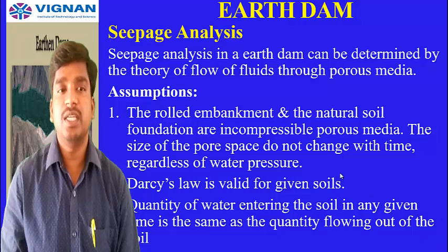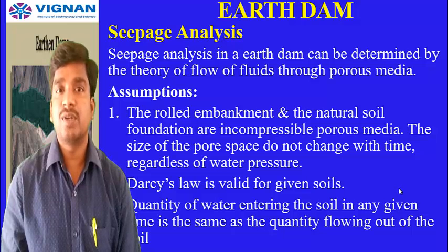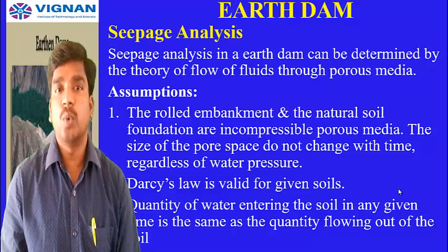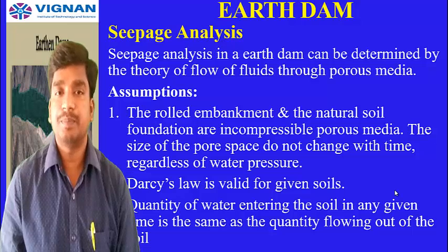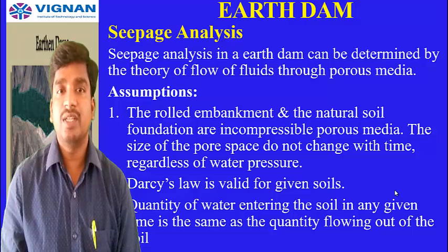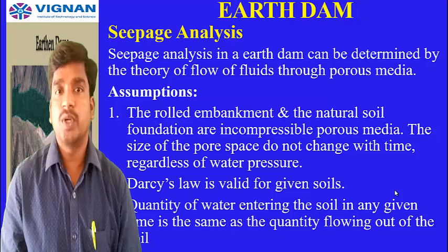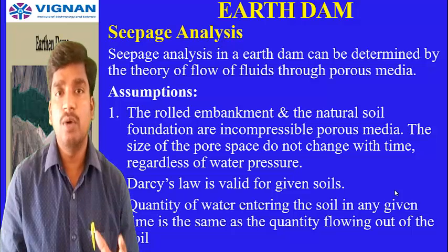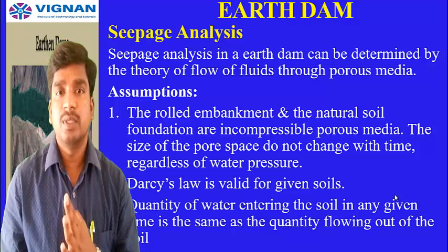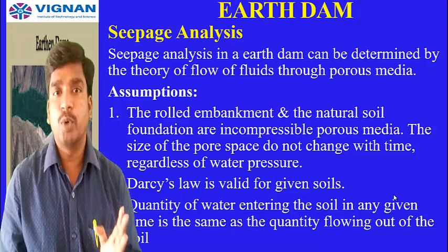So in order to analyze what the seepage should be and how the seepage can be controlled, we will discuss that now. See here, seepage analysis in an earth dam can be determined by taking one concept, that is the theory of flow of fluids through porous media. Whenever you take porous media, this is how the fluid flows through the porous media.